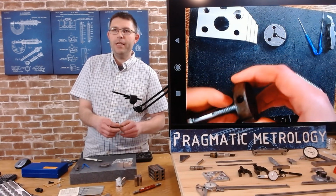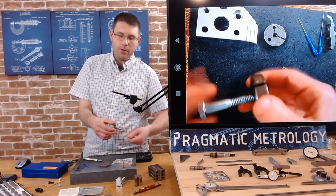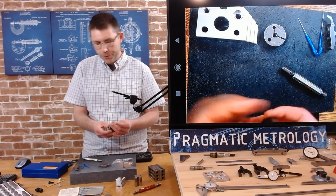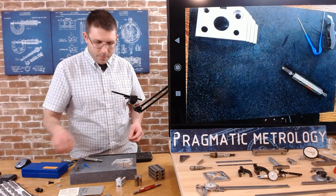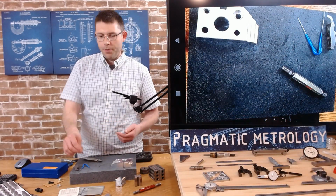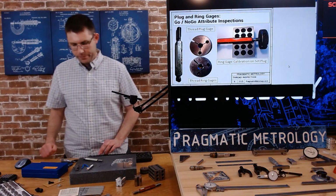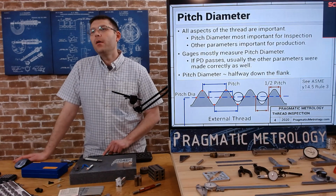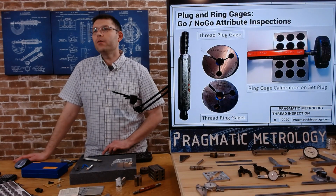There's usually a lead-in allowance for the first 3 threads. So if you can get 3 turns and stop, you're still passing with a NoGo. Otherwise, if the NoGo goes the entire length of the shaft, then your pitch diameter is out of spec. Oops, a little too far.